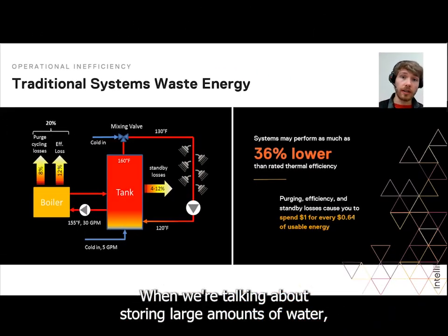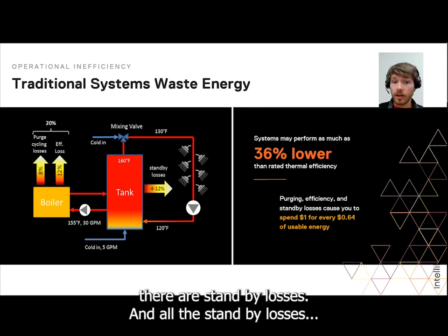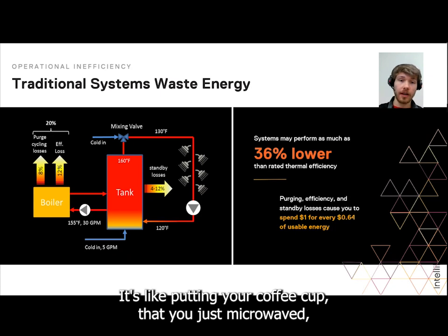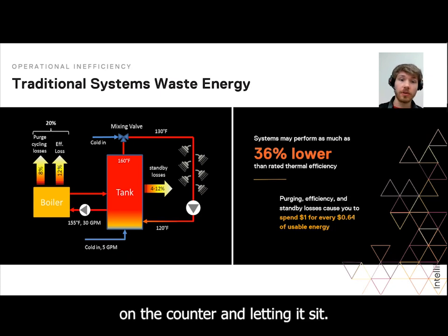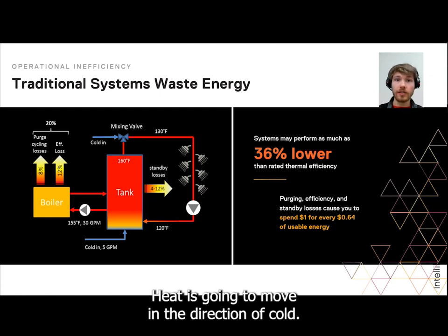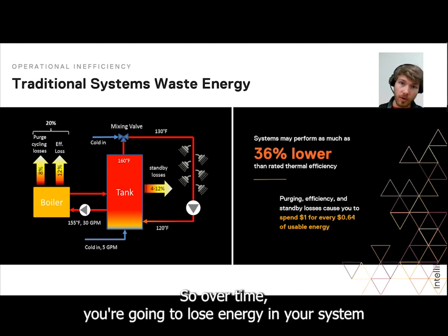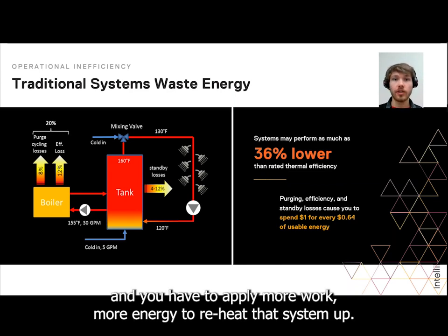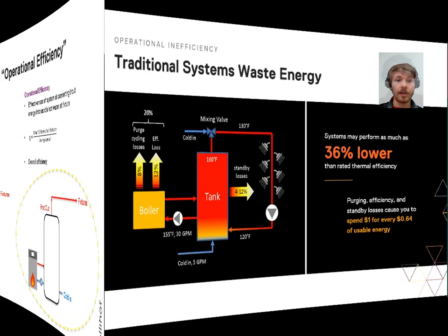We're talking about storing large amounts of water, there are standby losses. And all a standby loss is, it's like putting your coffee cup that you just microwaved on the counter and letting it sit, right? Heat is going to move in the direction of cold. So over time, you're going to lose energy in your system and you have to apply more work, more energy to reheat that system up.